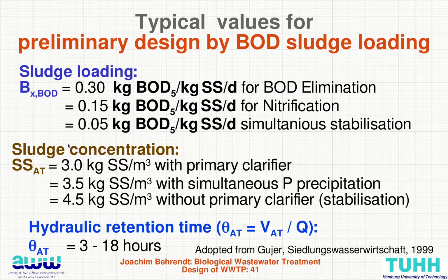Also these are the benchmarks, also typical values: 0.3 kilogram BOD5 per kilogram suspended solids for BOD elimination, 0.15 kilograms BOD per kilogram SS a day for nitrification.